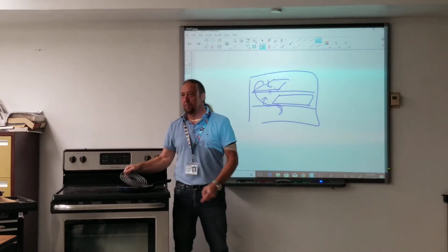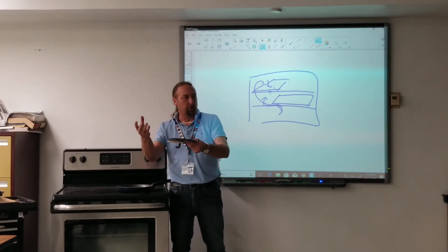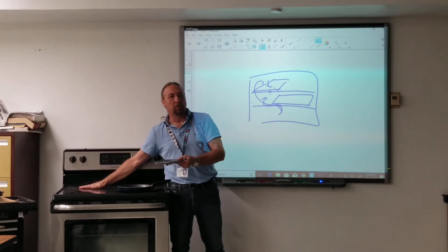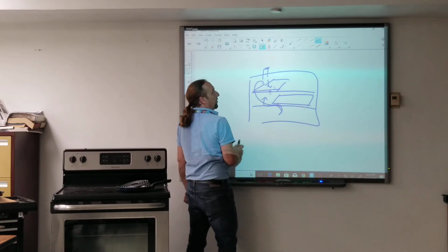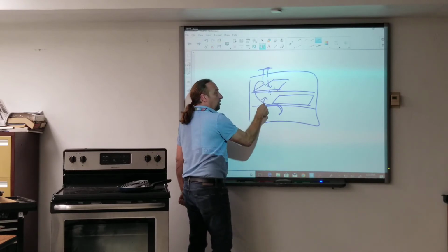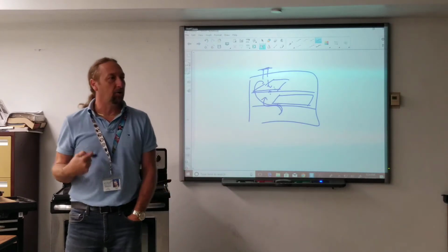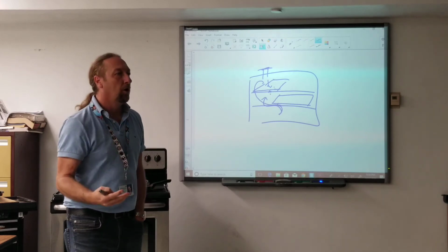The hole on the bottom is so that airflow can come up and we have a good airflow through it. But the oven vents through this rear burner. If you cover it with aluminum foil, you block that vent running underneath that burner, and you change the way the air flows in the oven. Now, if the lady's trying to bake a cake or bake things where airflow is important, she's going to get poor results.